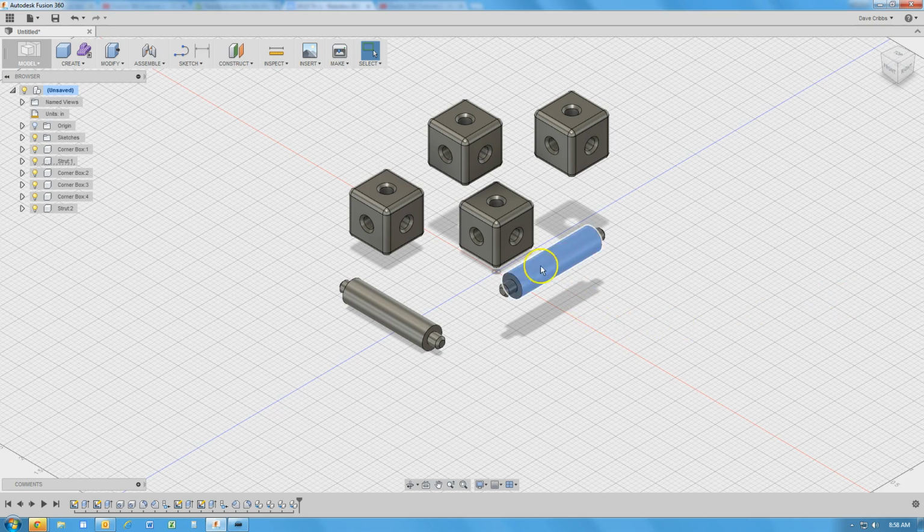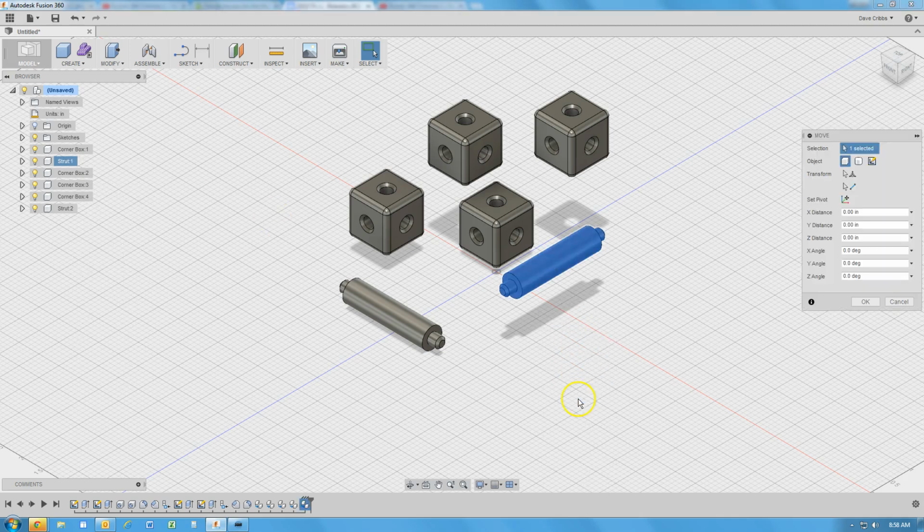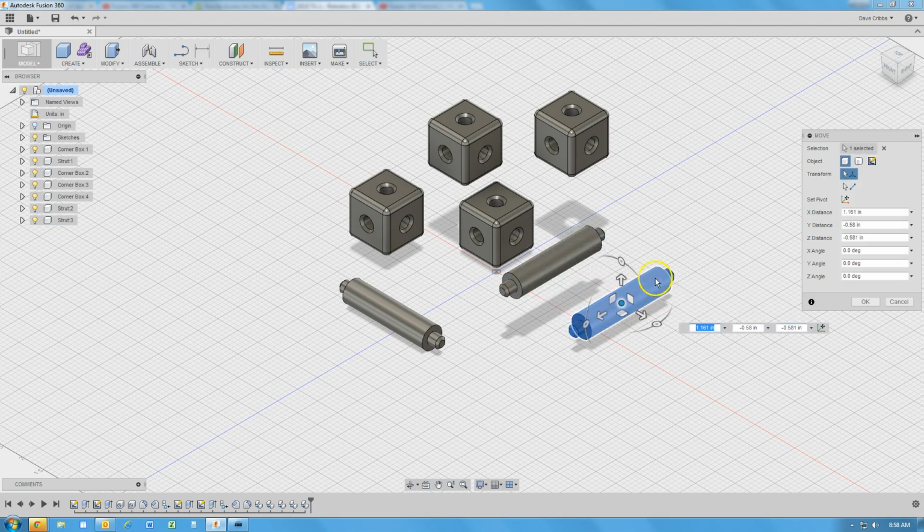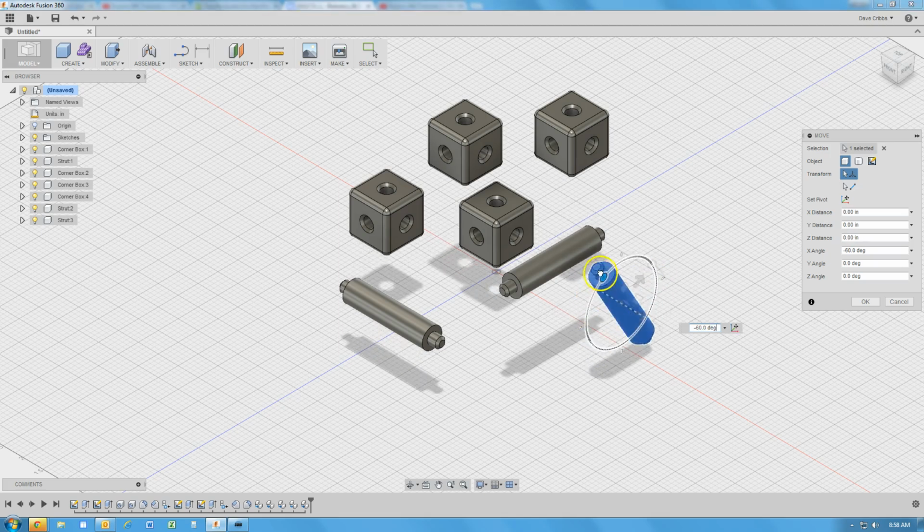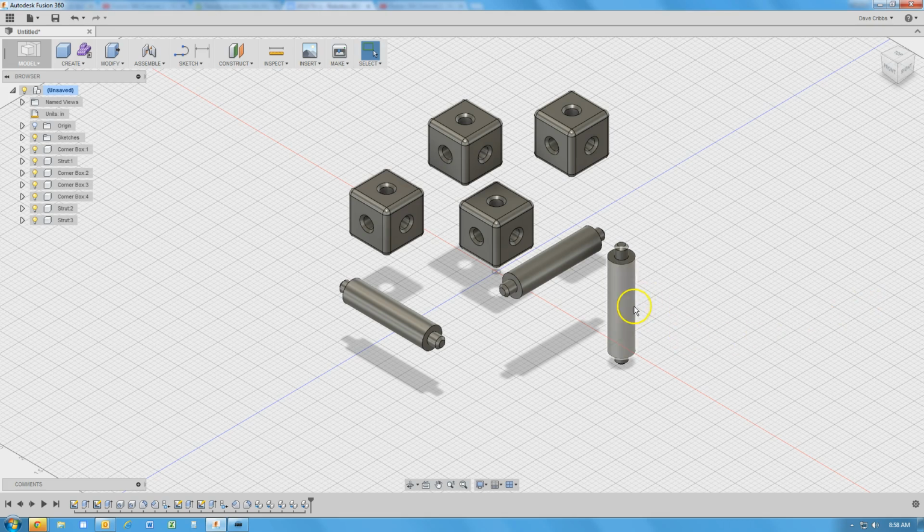I'm going to go back to this strut again. This is strut number 1. I guess I can just come back here, I can hit paste again. I'm going to take this strut. I'm going to rotate this strut vertically by 90 degrees so it can go in the top part of the cube. And eventually you'll need 4 of these vertical struts. You'll need 4 of these that are along the blue axis, and you need 4 of these along the red axis to complete the cube.